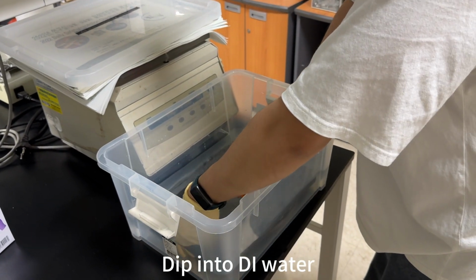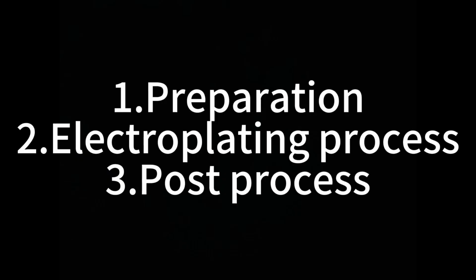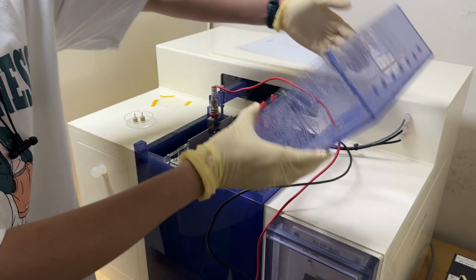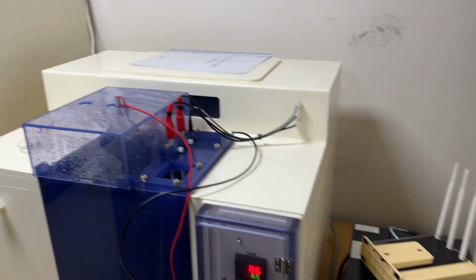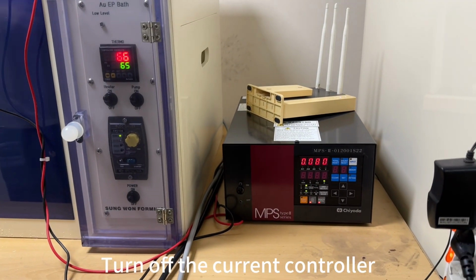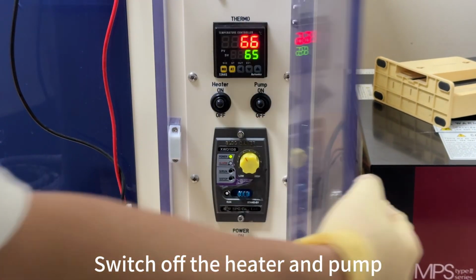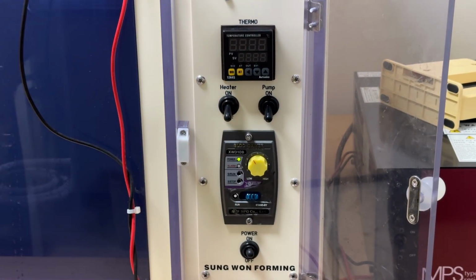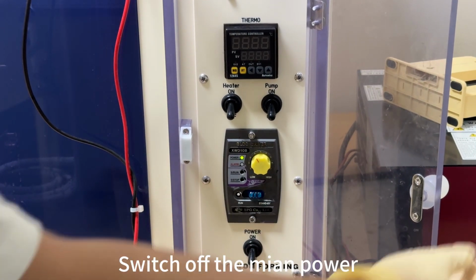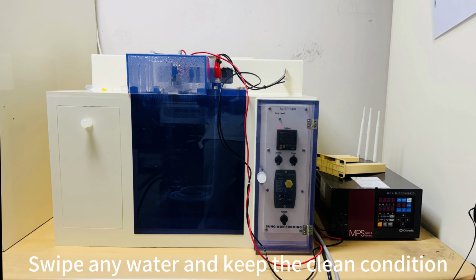Dip into the DI water. Close the lid. Turn off the current controller. Switch off the heater and pump. Switch off the main power. Clean around the machine. Wipe any water and keep the clean condition.